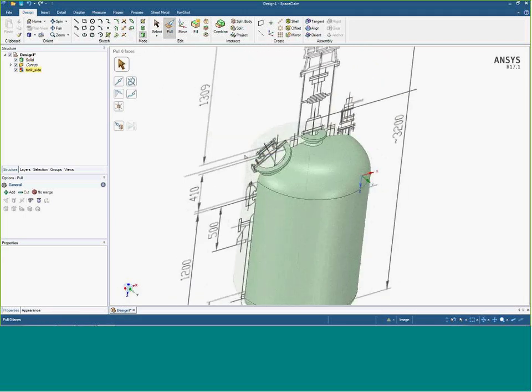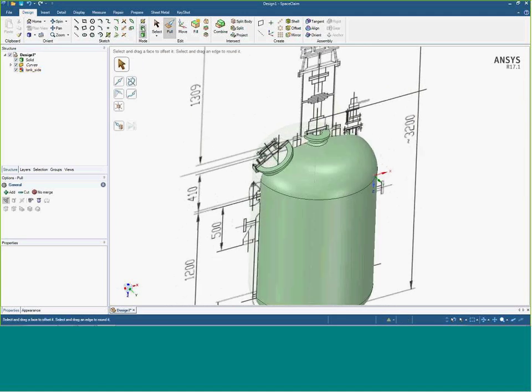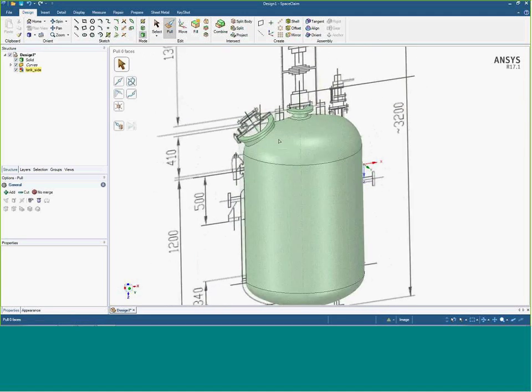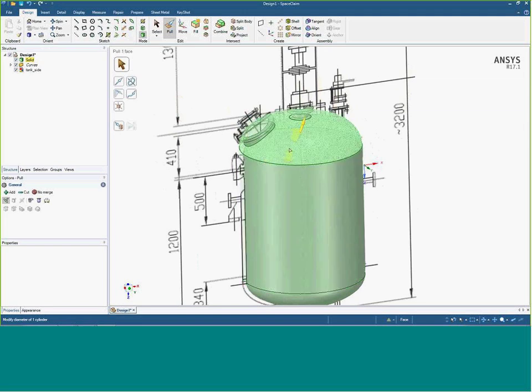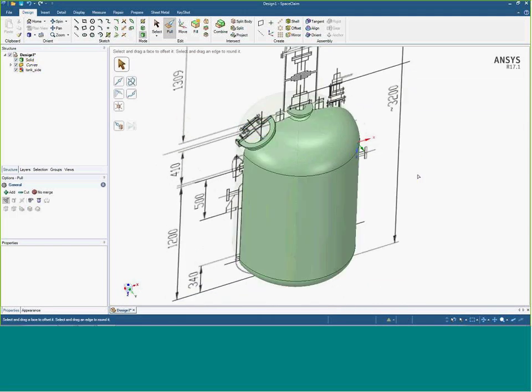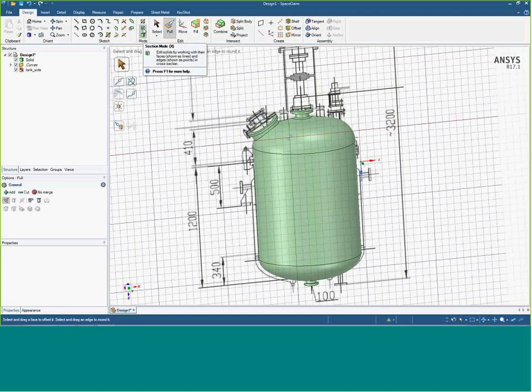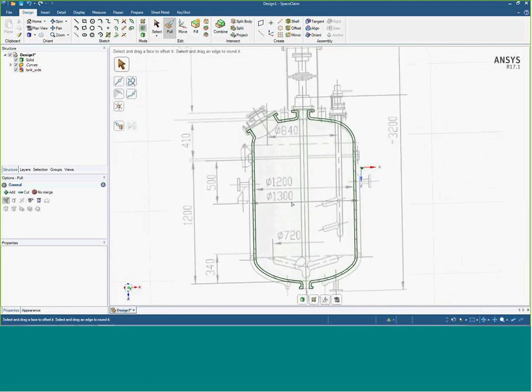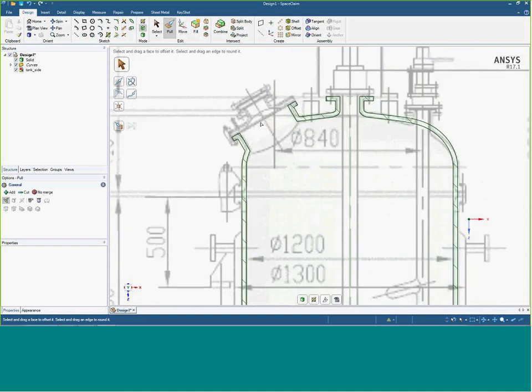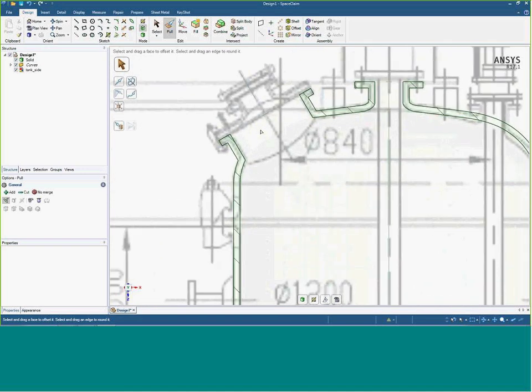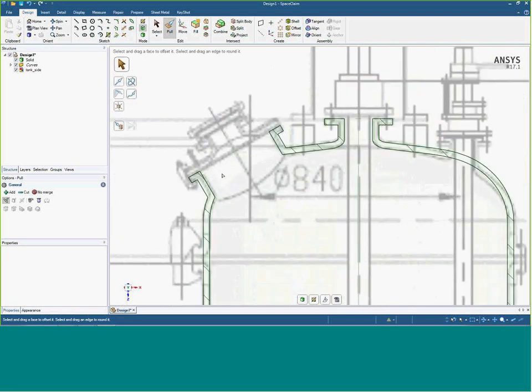The last mode of SpaceClaim that I haven't talked about is this cross-section mode, which we might want to use because now it's hard to see the inside of this vessel and our picture that we're using to draw things. So let's click the section mode, and it wants to know where this section is going to be placed. So I'm going to click the image again, just so it's parallel to everything that we've been doing so far with the image and sketch plane.